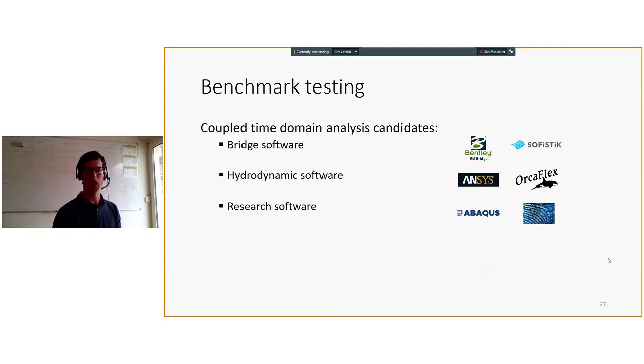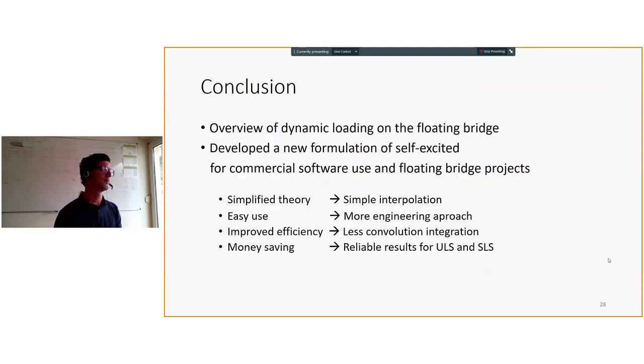I also came here to some conclusions. My goal was to have a decent overview of all dynamic loading on floating bridges. And as I briefly presented here, we have successfully introduced different formulations for hydrodynamics, wind, and currents, and all this in a new Newmark time integration scheme.